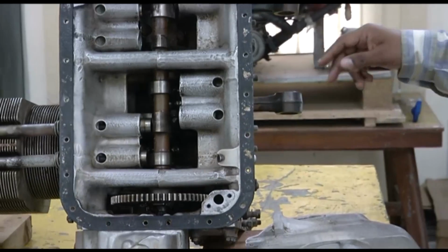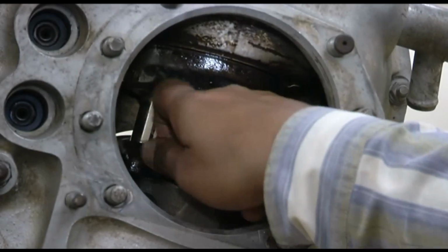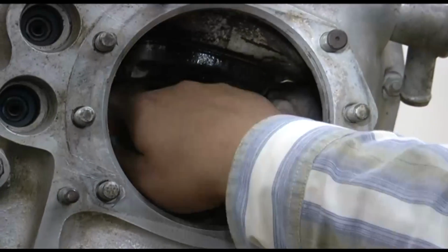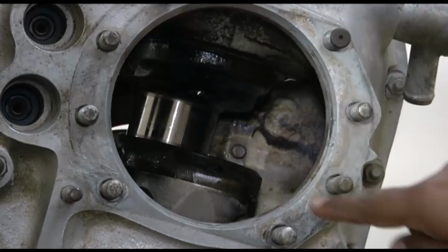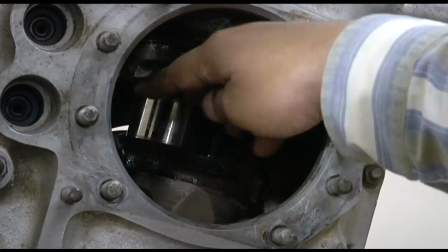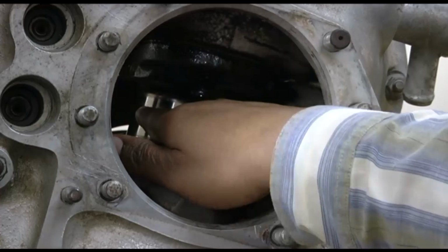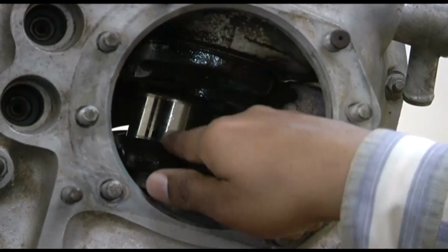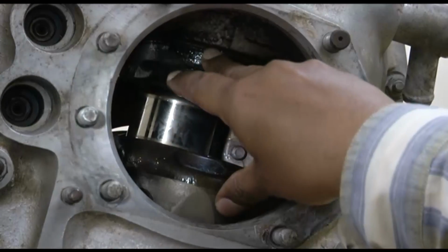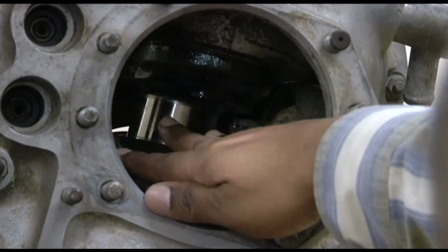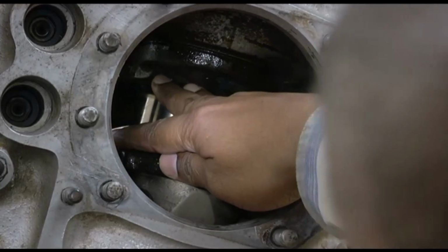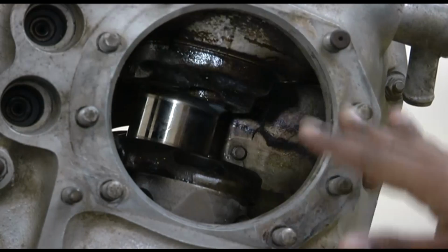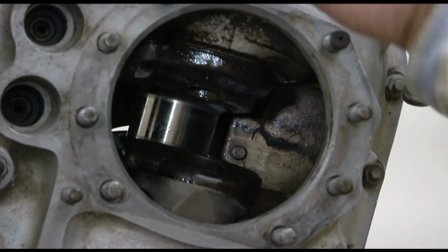So we will see the crankshaft. You can see here, this is your crankshaft, which is going all through. Here you can see this is your crank pin, which is part of the crankshaft. This is your crank cheek. Two crank cheeks and a crank pin make a throw. We have studied in the class what is a throw. So you can see the shaft here, one throw on this side, one throw here, one throw here. So basically this is a 6-cylinder engine. So 3 throws on this side, 3 throws on the other side.